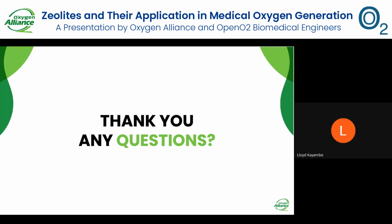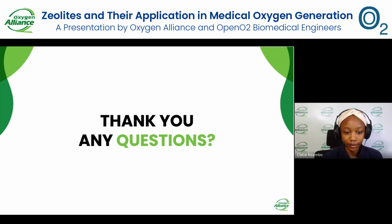Yes, I have. Maybe just to add on, larger volumes of the sieve bed generally mean that there is more zeolite and more surface area for absorption. This will hasten the absorption of the nitrogen, which results in production of more oxygen. So I would say the tank volume can also influence the production capacity of the PSA generator. I hope that has answered your question.